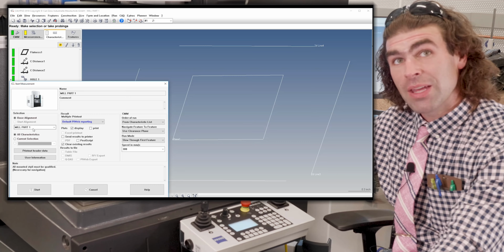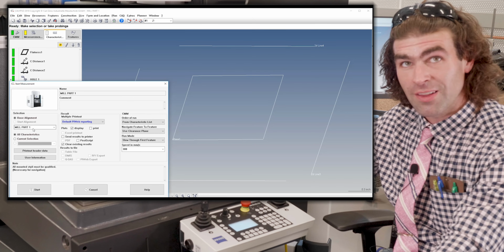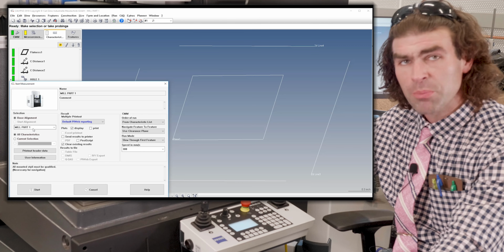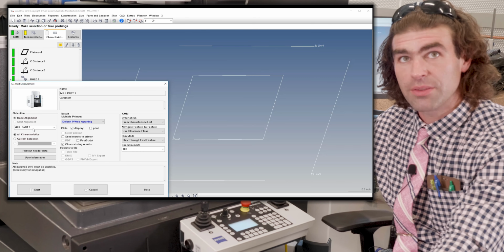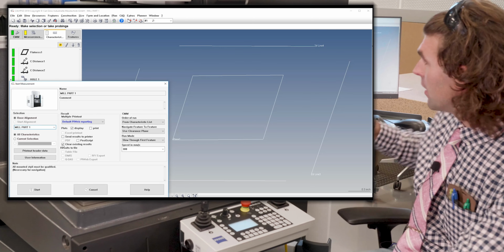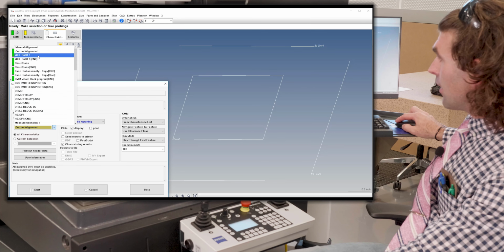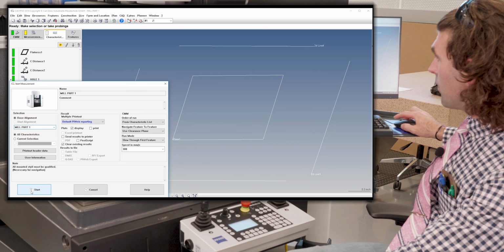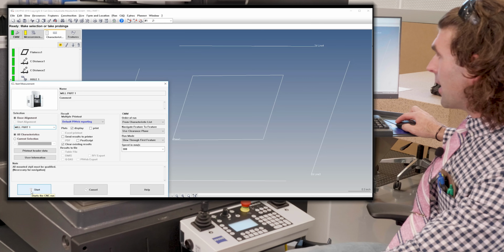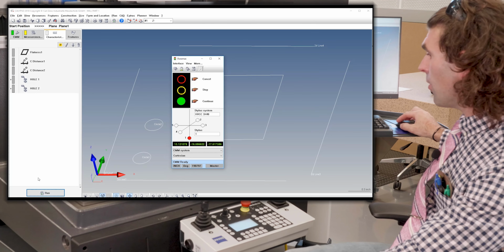Maybe somebody came in last night and tilted this by a quarter inch. If you run with current alignment, the computer might smash into something. So it's good to run the alignment from the program you've got loaded up, right? So I want this box checked, the clear existing results, right? And I'm going to hit start. All of the other settings we'll leave as default.